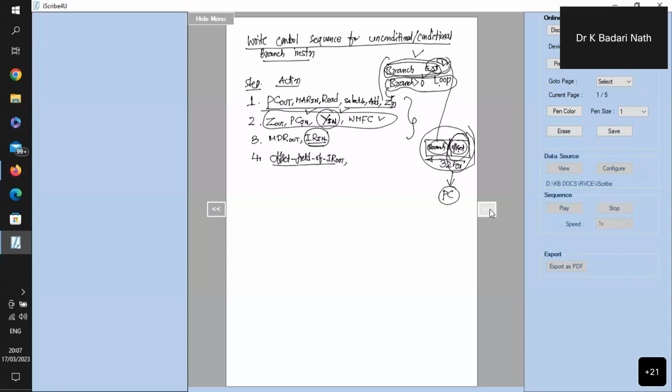It is required only in case of a branch instruction, because in a branch instruction we are jumping to the new location by adding to the existing value of the program counter. The program counter always points to the next instruction to be executed. PC plus 4 is already there here. But instead of bringing it again from the PC and performing an addition in the fourth clock cycle, we can do this: Y is a temporary register and it is free now. Along with updating the new value to the program counter, write that into Y also.